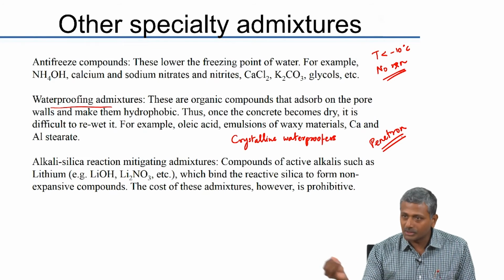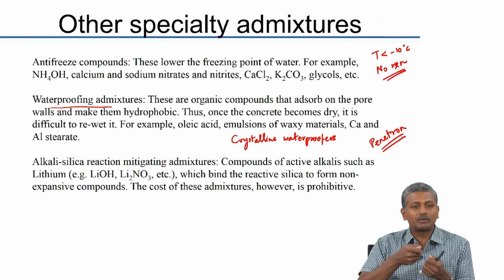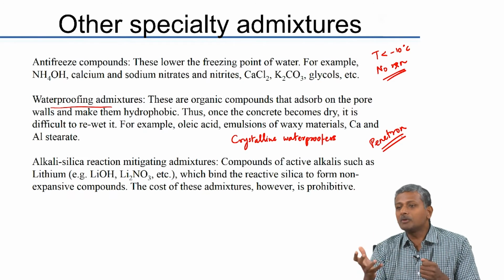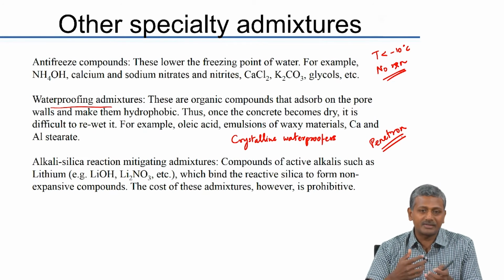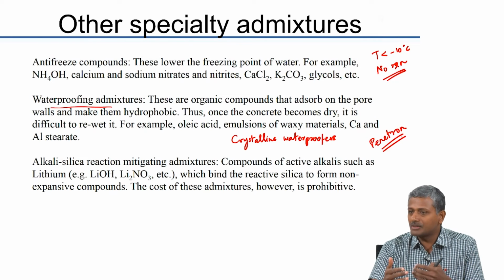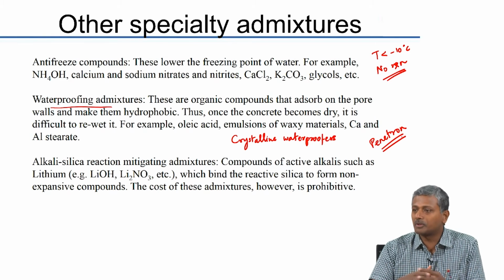So, it was actually gushing through the concrete, and what they tried to do, they tried to plug the concrete by putting grout into the concrete. Now, the problem is, grout, you can apply any pressure that you want, but grout can only go if there is a cavity or a void present for it to go. If the concrete does not have cavities or voids, grout will not go anywhere. So, again grouting did not prove to be quite effective and so on.